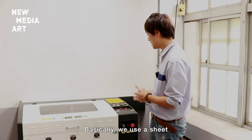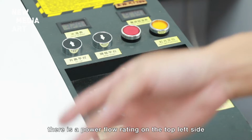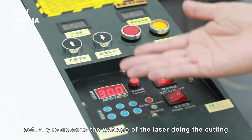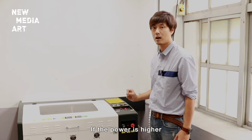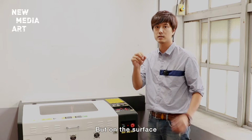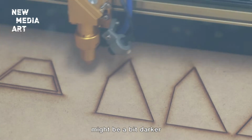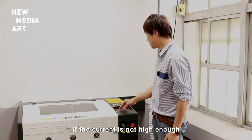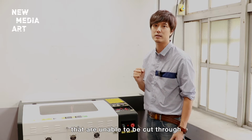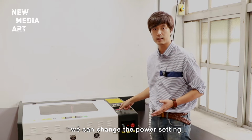Basically, we use a sheet to give a brief introduction. First, we can see that there is a power flow rating on the top left side. This rating actually represents the wattage of the laser doing the cutting. If the power is higher, then it can cut thicker material. But on the surface, for instance with wood, the burnt parts might be a bit darker. If the current is not high enough, then there might be some places that are unable to be cut through. So for sheets of different thicknesses, we can change the power setting.